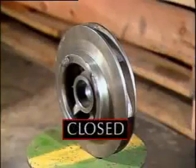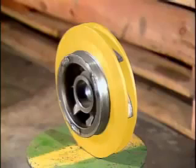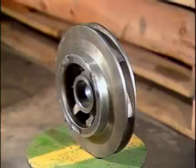This impeller is a closed impeller. Its vanes are enclosed by shrouds on both sides. The shrouds direct the flow of liquid between the vanes. Closed impellers are often used with low viscosity or thin liquids. Liquids that are thick or contain suspended solids could clog a closed impeller.